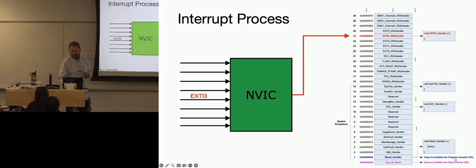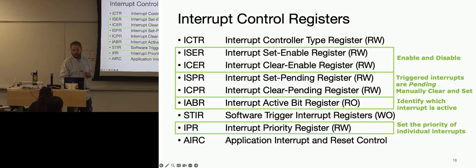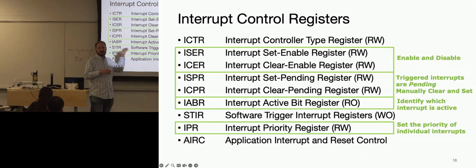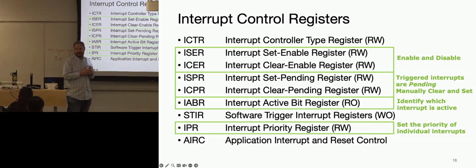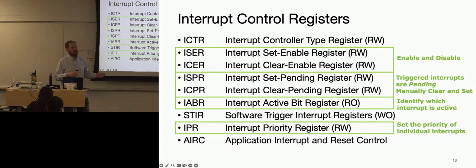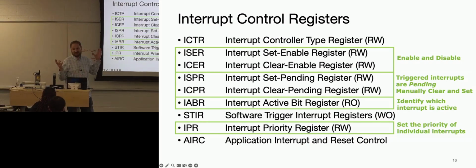Yep. So where default states are not known? It's default to a certain state that you should go for. So the manual will tell you what the default state of registers are. You might not like them. They might not help you execute your program. It could be you don't want to boot up and then have your motor starting to turn. That would be annoying. And so as soon as your thing boots up, the first thing it does is reset the direction of those pins, for instance. Now that's less of a worry on this particular microcontroller.